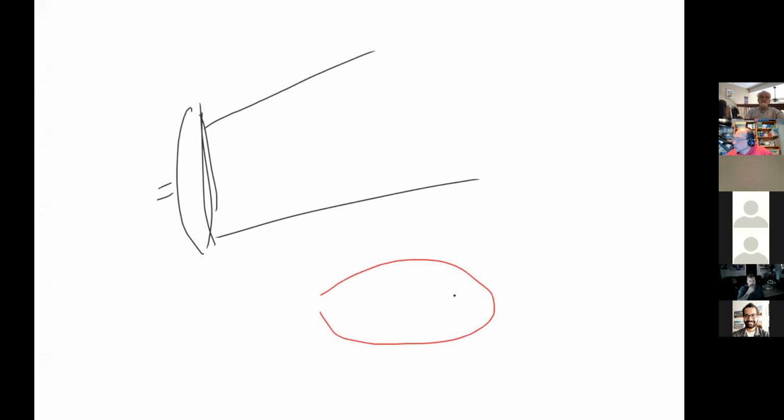That typically is going to have a fairly narrow beam width of the signal coming out of it. If we were to plot the pattern of this antenna, we would see that it looks something like this, with a little bit going back. Here's the peak right here. We also have a definition to define the beam width of this antenna pattern. Typically, this is known as the half power point.